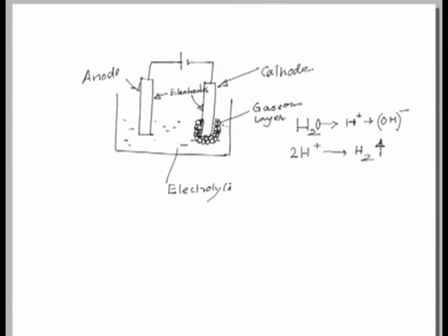This is called the passivation effect, which is nothing but a byproduct of the dynamics of the process. Now, for having effective machining or working of this process or the cell, we need to remove this gaseous layer, so that the cell again starts functioning.